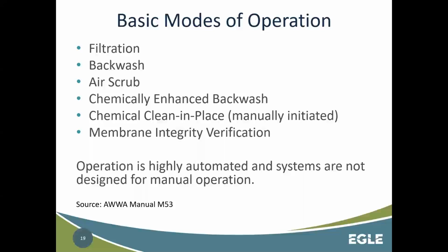But this is an example of common modes of operation. Filtration, backwash. Sometimes that backwash has compressed air introduced. They call that an air scrub, so it kind of enhances the backwash. Then there may be a chemically enhanced backwash. So it's the same thing as a backwash, except maybe they introduce chlorinated water.